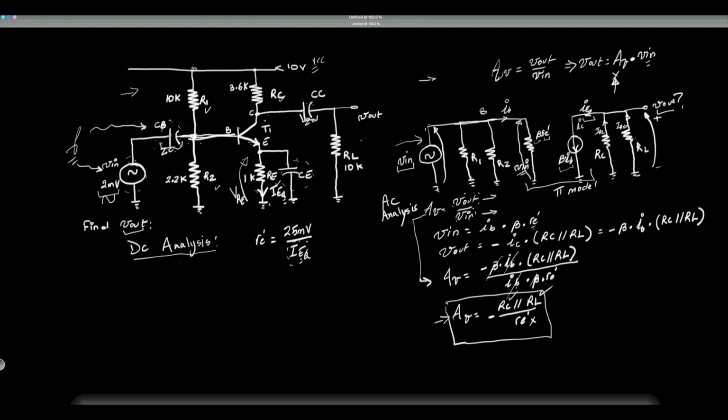Okay, well, what else do I know? Well, I have a voltage VBE here, and that's approximately, this is DC, approximately 0.7 volts. And look at this point right here. From here to here, I also have a voltage. Or, even better yet, from here to here, I have a voltage. These two add up to VCC. But we're interested in this one. Since if we apply Kirchhoff right here, and do a node analysis, this total voltage will be equal to the sum of these two.